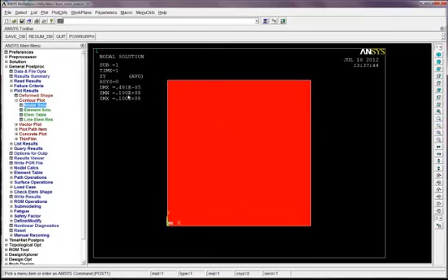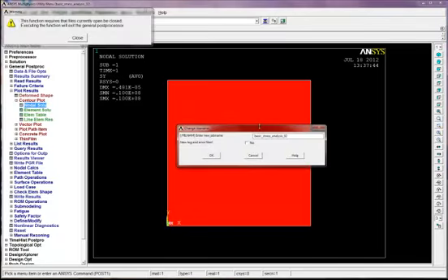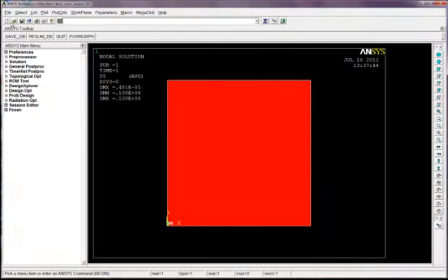But how do we know if the value we got is correct? Okay, so the first thing we have to remember is that stress is load over area. So we've applied a load of 1000 newtons. Again, if we don't know how we've applied that, let's go and find out how we can do that. Before I do anything, I forgot to actually change my file name, remember? So the first thing I do, file, change job name, and this is number 3, so let's just change this to number 3 and just go save, just so we don't overwrite the other files.